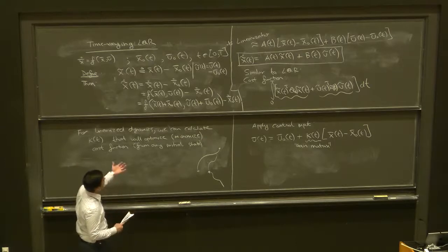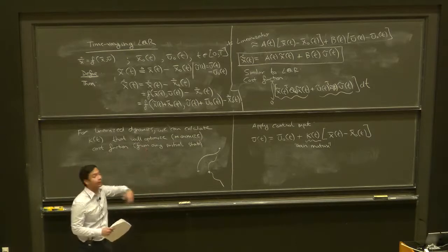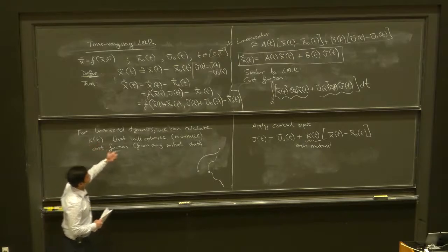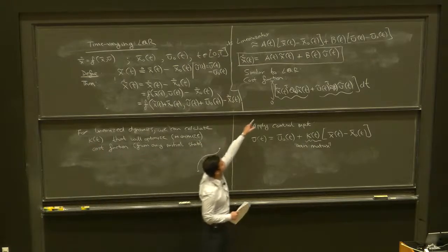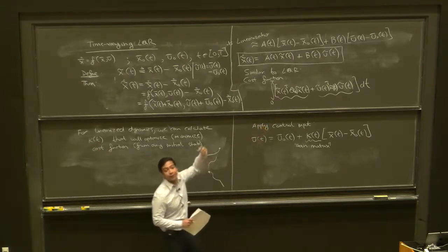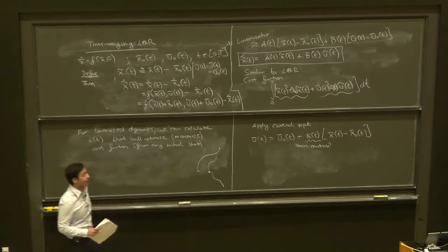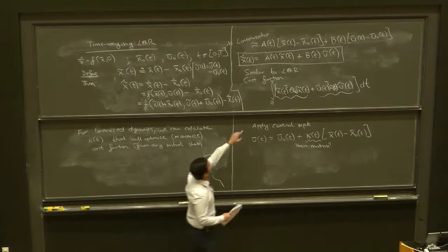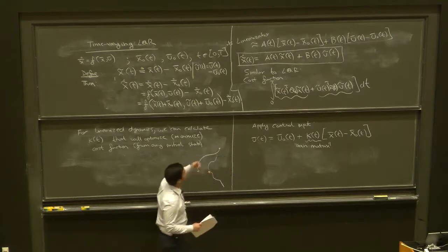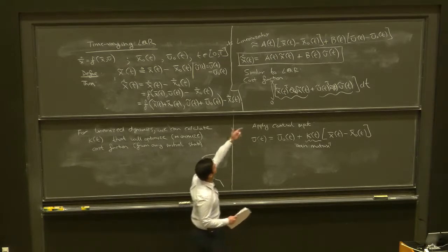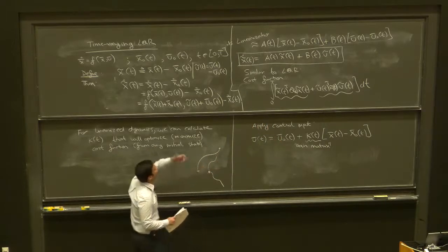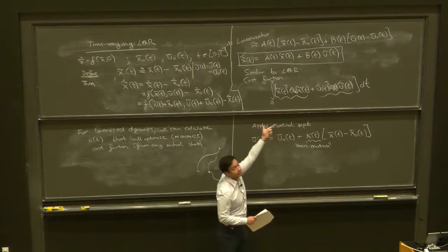What I'm claiming is that I'm going to describe a procedure for calculating a particular K of t that's going to optimize this objective from any initial condition that you start off in. So for any initial condition, in principle, you can run the feedback controller, calculate the states and control inputs that result from applying it, and that quantity is just a scalar, right?